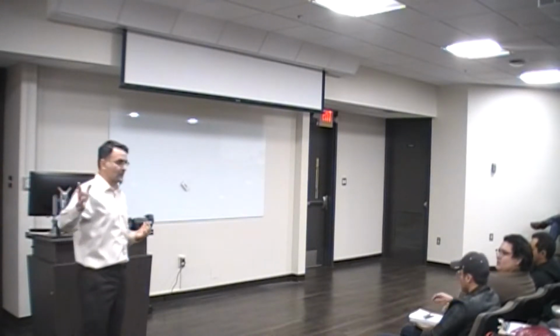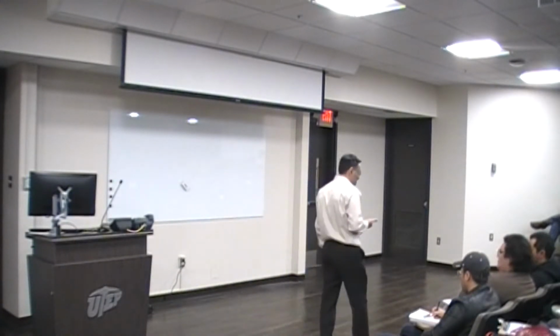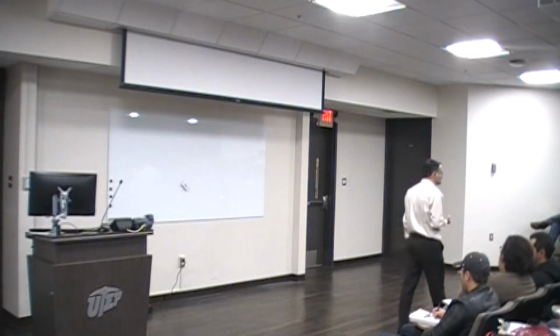If you want only one takeaway from this lecture, it is that soils are frictional materials, as opposed to other materials that you're familiar with, such as concrete or asphalt, where there is a glue in between.